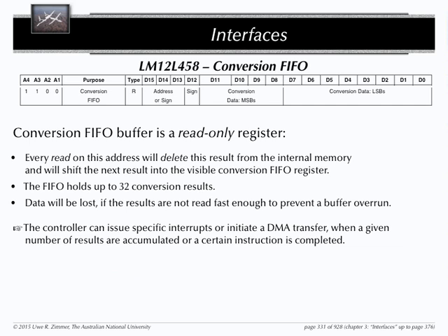The FIFO register is read-only. Surprise, you cannot write into it. But it also means that every read operation, as we said before, into that register will give me the oldest value in my buffer and immediately deletes it. So not only write operations on hardware have side effects, read operations have side effects too.